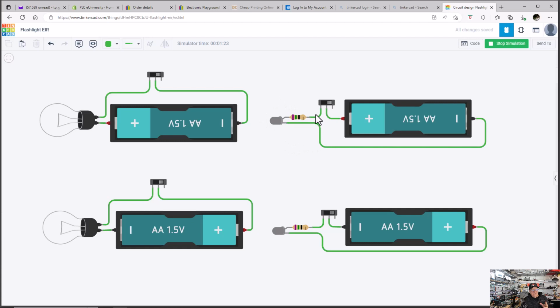But you don't see this when you have an LED flashlight. So what I did was I flipped the battery around to show that it doesn't matter which way you put the battery in with an incandescent flashlight, as long as the contacts make contact. Now, they won't in most flashlights. If you try to put the battery in backwards, it won't make contact like it's supposed to. But let's turn this one on, and you see that for both of these incandescent flashlights, whether the battery's in one way or the other electrically, not mechanically, but electrically, the bulbs light up.